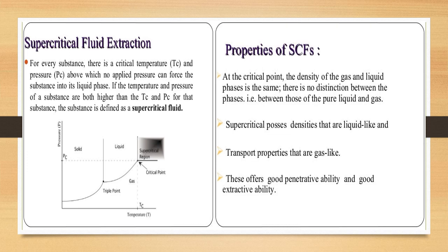There are some properties of supercritical fluid. At the critical point, the density of the gas and liquid phases is the same. There is no distinction between the phases, that is, between those of the pure liquid and gas. Supercritical fluids possess density that is liquid-like and transport properties that are gas-like. Moreover, this offers good penetrative ability and good extractive ability.